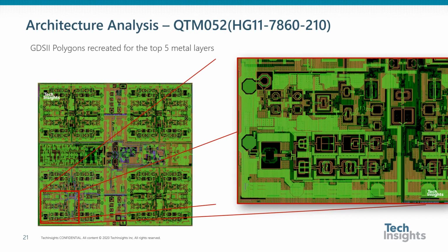This analysis takes advantage of the fact that characteristic layout features such as high-speed signal routing, inductors, AC coupling capacitors, and balanced circuit design practices are easily identified with the use of lower resolution SEM mosaics of the upper 5 or 6 metal layers and the polysilicon layer of the device. Couple this with the experience of the analyst and we can extract the high-level architecture of the device, which really is a block diagram of the transceiver, like what you might find in a datasheet if they existed, which for the most part they don't.